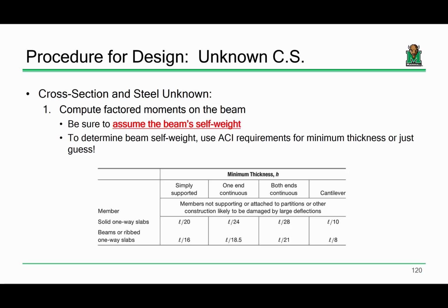Does that work for units or doesn't matter? Sorry, what? It doesn't matter what the units are? Well, no, that's a good question. So if the span length is 20 feet, what's 20 divided by 16? What are the units? Oh, yeah. Feet. So if you take 20 divided by 16, you're going to get 1 point something feet, or however many inches. Okay. Yeah. So just be cognizant of your units, that's for sure.